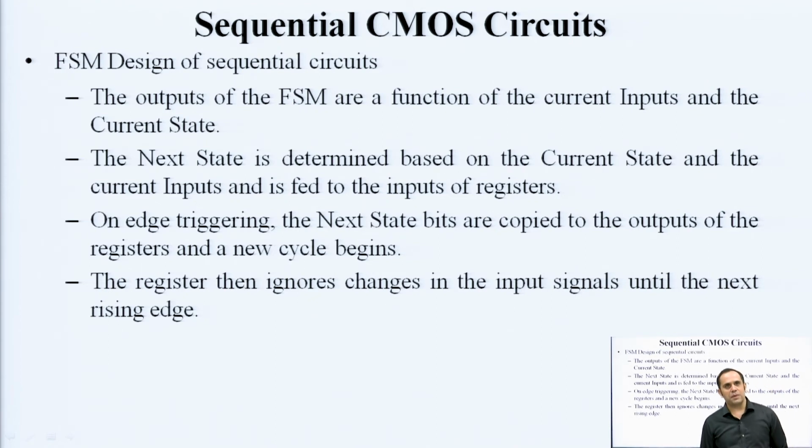The most common approach for a sequential circuit is what is known as FSM. As I said, FSM stands for finite state machine. Every word has a meaning. Finite means there is a limited number of something, and that something is the states of the machine, and machine means the sequential circuit. So, any sequential circuit which exhibits a finite number of values or outputs can be considered to be an FSM.